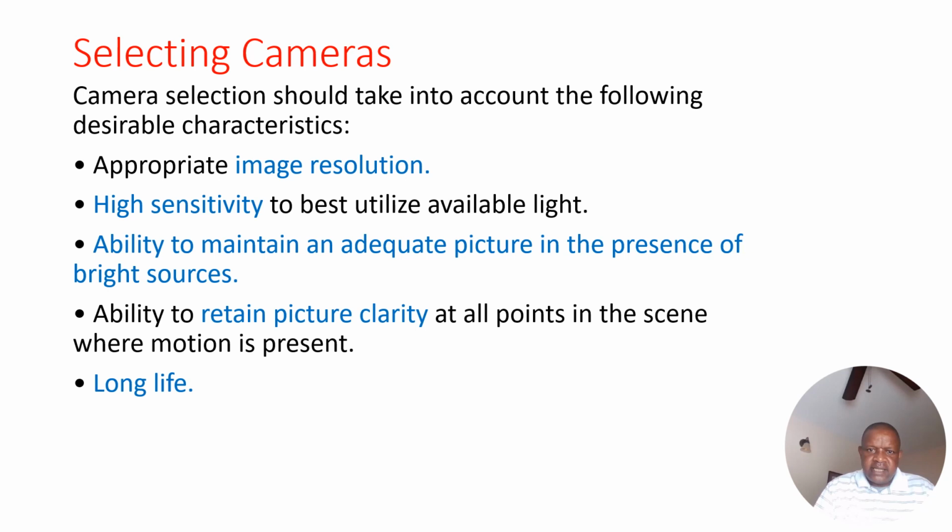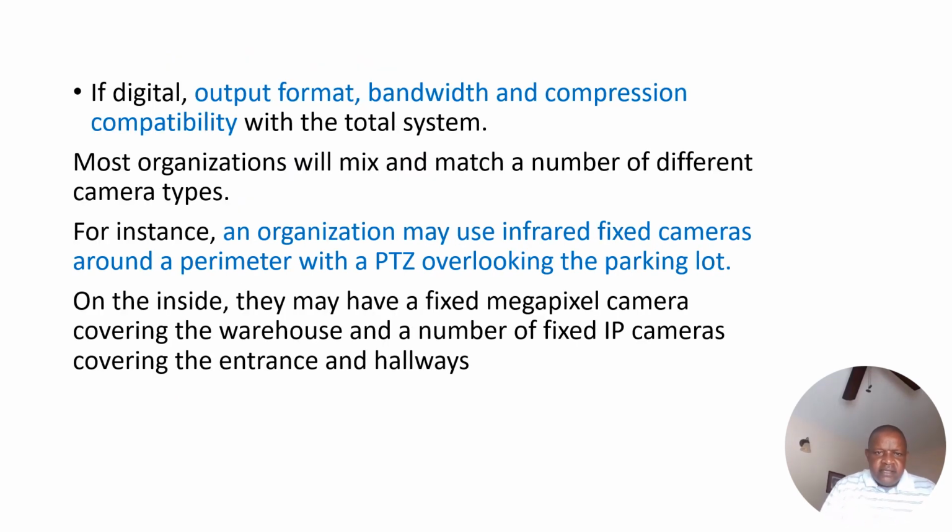Ability to maintain an adequate picture in the presence of bright sources. Ability to retain picture clarity at all points in the scene where motion is present. And then long life. Definitely you need cameras that can give you a long life. And then, if digital, output format, bandwidth, and compression compatibility with the total system.